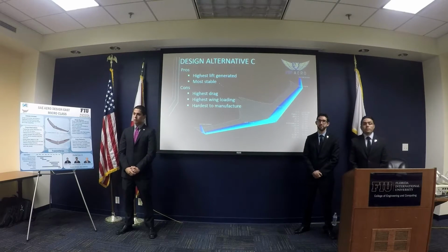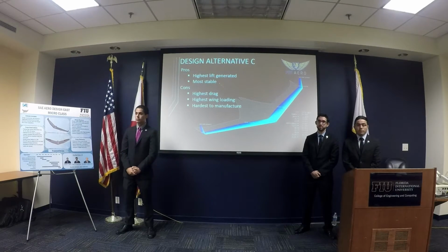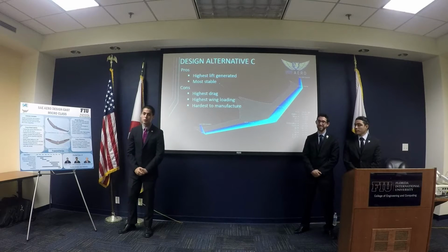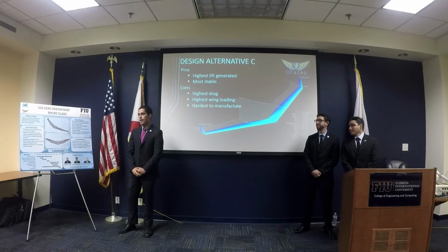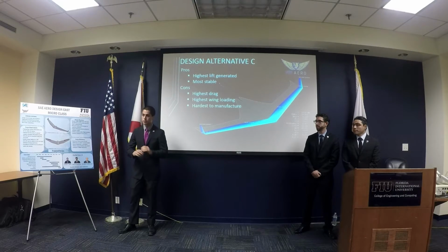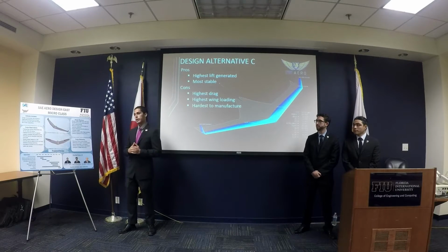So if you're doing modularity, first of all, do you have control surfaces? Yes, sir. So if you're having modular wings, how do you connect your control surfaces, electrically? Great question. Okay, so we can do either one of two things. We can have some sort of banana plugs or some sort of plugs that we connect halfway to the back. We connect the wings, we connect the plugs. There we go. Or if budget permits, what we're thinking of is having contacts.